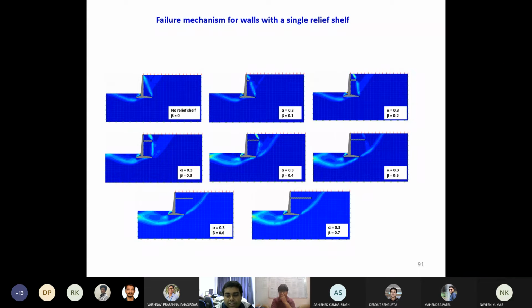And whenever you have a shelf or any point of different materials of different stiffness contrast protruding inside, at that time you will have a point of stress concentration from where the stress starts to dissipate. And that's where in these particular cases you will see two different types of failure patterns which originate. One moves towards a stiffer material, one moves inside and through the less stiff material. And that's exactly what we are seeing in this particular case.